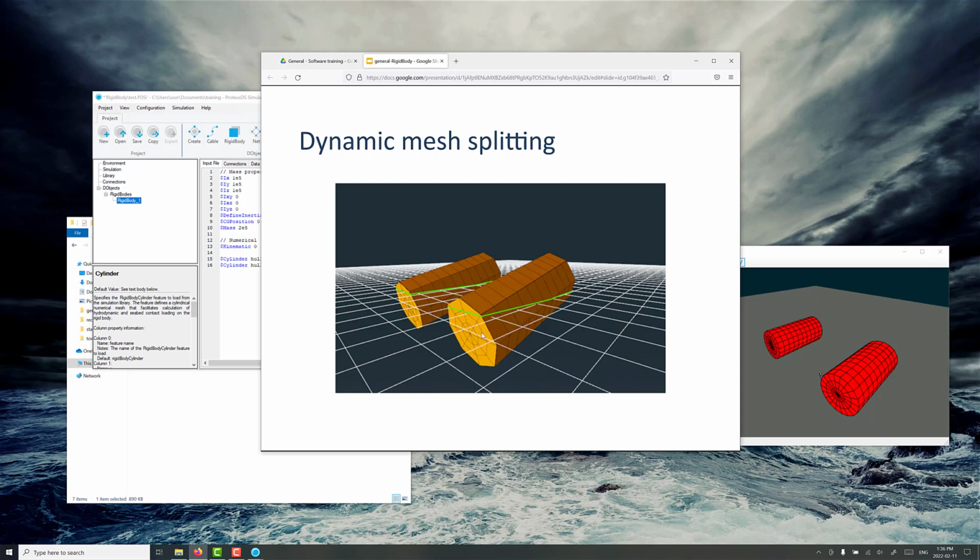So even though it looks like these cylinders are quite a bit more coarse than this, a lot of effects like buoyancy, the changing buoyancy, and wave excitation and wind loading will actually be quite a lot more well distributed than initially it looks like. So that's a really good balance of computational performance.